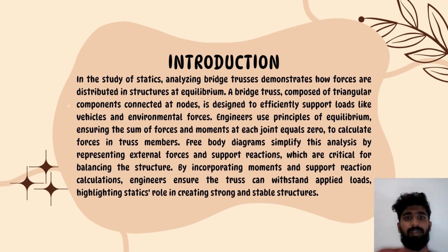Engineers use the principle of equilibrium, ensuring the sum of the forces and moments at each joint equals zero, to calculate the force in a truss member. A free body diagram simplifies the analysis by representing internal forces and support reactions, which are critical for balancing the structure. By incorporating moment and support reaction calculations, engineers ensure the truss can withstand applied loads, highlighting statics' role in creating a strong and stable structure.